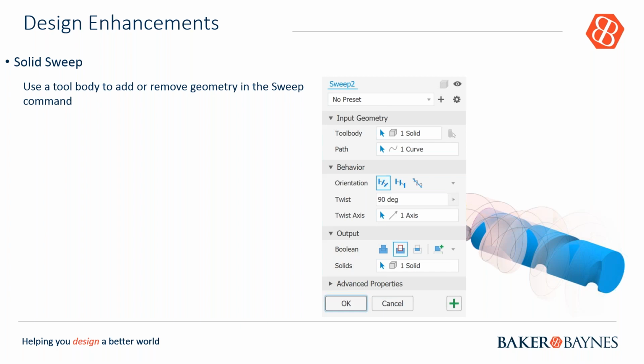This increases both performance and success with the computing power. If the sweep fails to compute, try removing tool body fillets. In some cases, it may help to add fillets. Okay, the helical curve command creates an associative center axis you can select in the direction vector and aligned sweep. All right, so there's been a nice enhancement on this side.